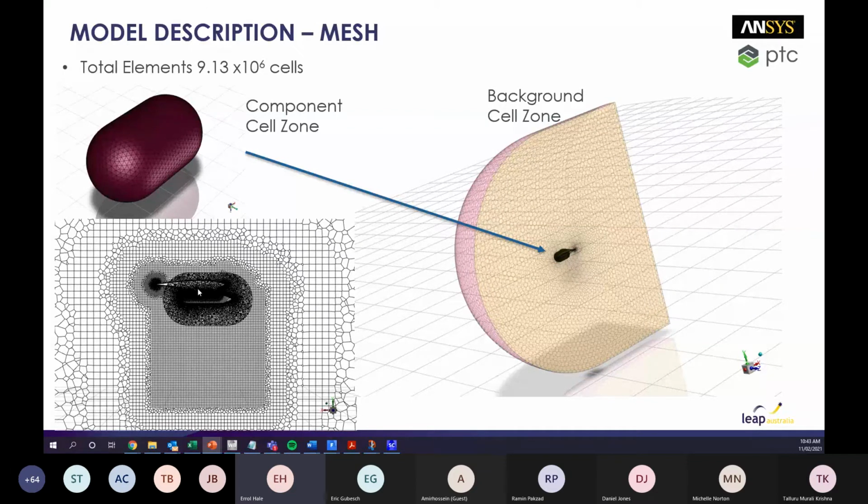If we don't do it with overset, we have everything in the same grid. As the store drops away, we have to remesh the domain constantly at each time step. And that can cause problems, well, it doesn't cause problems, it's just a different way of doing things. There are different difficulties involved with having an overset grid and a dynamic mesh grid. In a dynamic mesh grid, you need to make sure your remeshing settings are such that you're getting the same definition of grid every time it remeshes, and that your diffusion methods, or whatever methods you're using, are working correctly and your parameters are specified correctly.